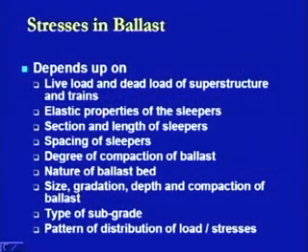Now, once we have discussed the stresses in the sleepers as well as the stresses in the rails, the next thing which comes in continuation is the stresses in the ballast. Now, stresses in the ballast will be dependent on certain factors. The first factor is the live load and the dead load of the superstructure and the train. The superstructure here means that we are providing the rail section and the sleepers above the ballast cushion. So, whatever is the load of all those things along with the live load of the movement of the rolling stock, we have to take into consideration all these loads, and on the basis of that the stresses are going to be induced in this section.